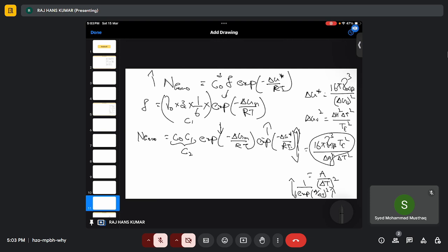The number of jumps will also decrease. So atoms will be more sluggish to diffuse. So there are two opposing terms here. If I decrease the temperature, the undercooling increases and the homogeneous nucleation rate will increase, but the diffusion of atoms will decrease.